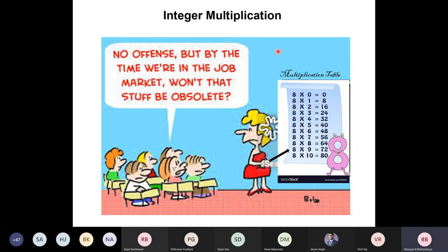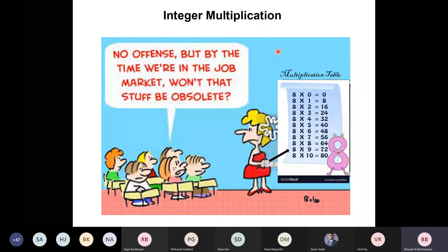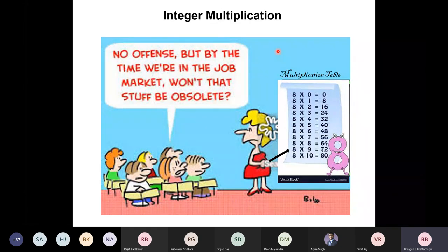We identified the carry recurrence relationship, and that enables us to write the Boolean expression for the carry signals in terms of inputs, G's and P's. Following those Boolean equations, we can design our hardware accordingly, but that becomes expensive.